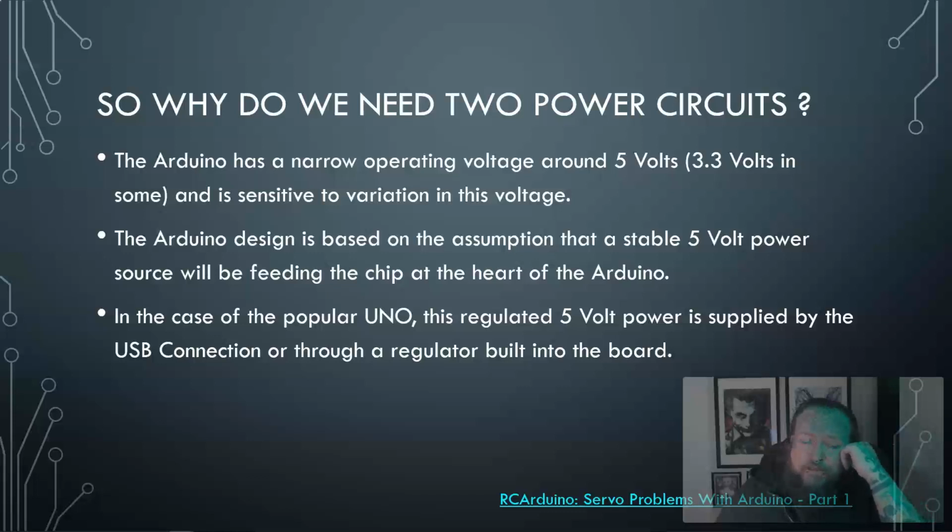You need to have a separate power source from this, because even when it's connected through USB, like we've been doing generally, that's one level of power versus powering it from an actual battery. And that's where, again, when you start adding more and more motors, not like this week, but if we had more in the future, then you're going to have separate circuitry between the two of them, and basically some power sources.